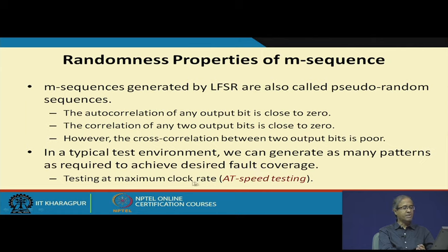The good thing is that we are able to test at the maximum clock speed. This is called at-speed testing, where some faults which arise because of delays in the circuit, the critical timings, will also get detected. In scan designs, we are not detecting such kinds of faults.